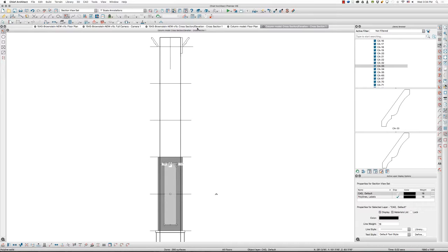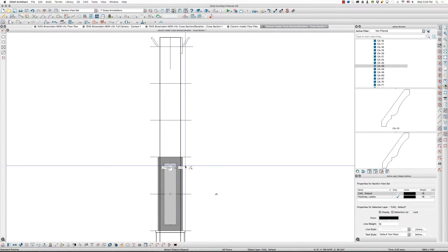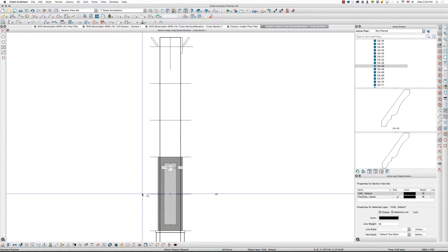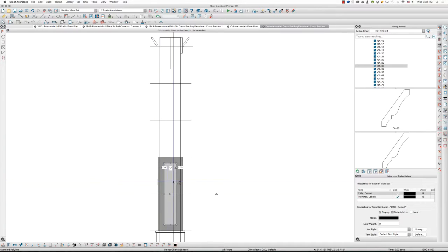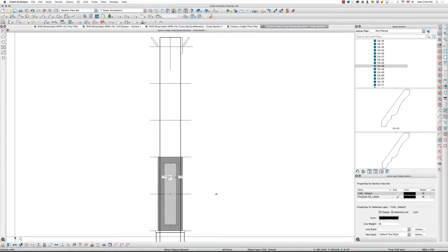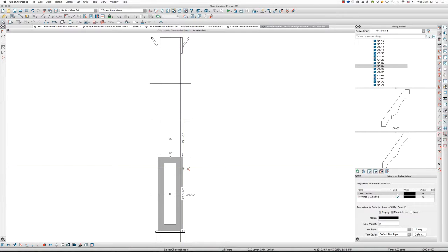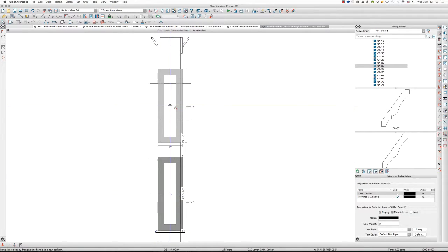Now I've got the hole selected. I'm going to shift click. Sorry, that didn't work. Okay. I'm going to do this again. I've got the standard polyline selected. I don't want that right now. I want the hole. So I'm going to tab on my keyboard. Now I've got a polyline solid. I'm watching the lower left-hand corner of my screen, which tells me what that object is. Now I'm going to shift click, and now I've got 2 objects selected. I'm going to copy both of these objects up here.